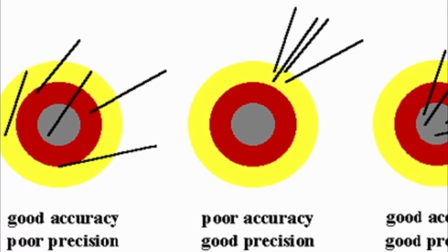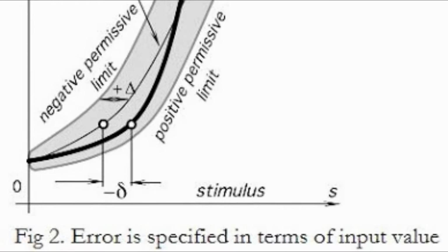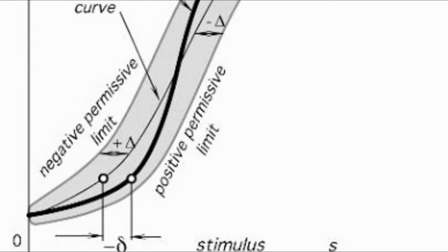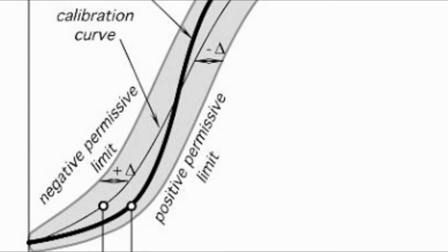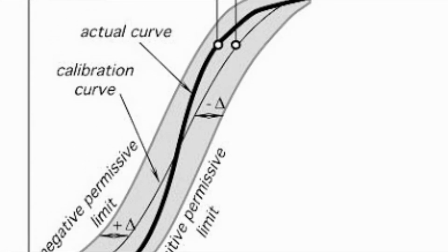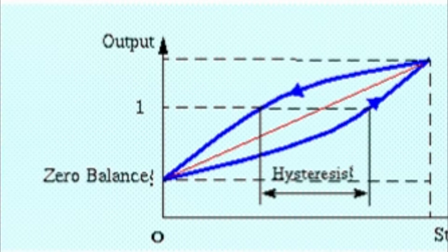Resolution. The resolution of a sensor is the minimum change in the target property that can produce a detectable change in output. For example, consider a temperature sensor with the resolution of 1C. This temperature sensor cannot produce a different output for a 0.1 C change in input.